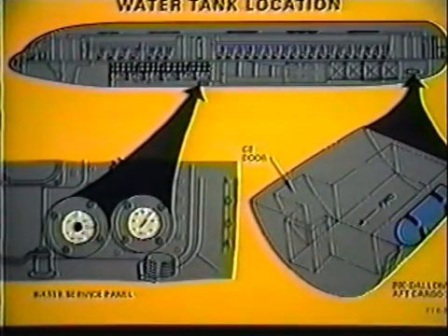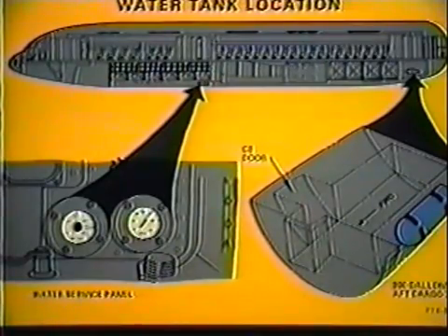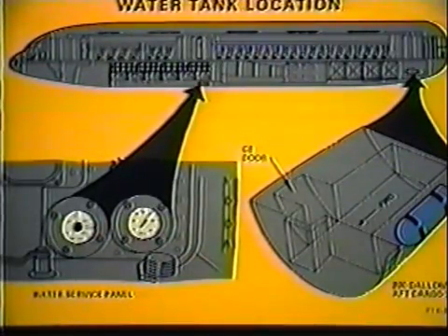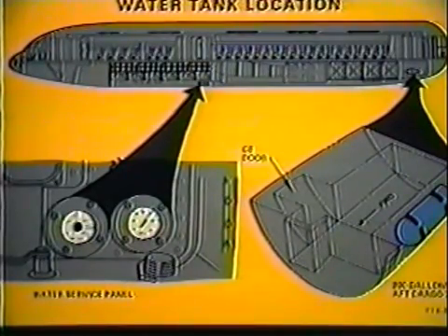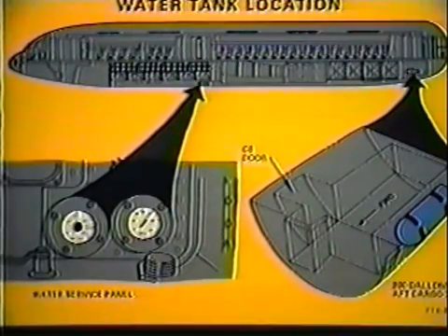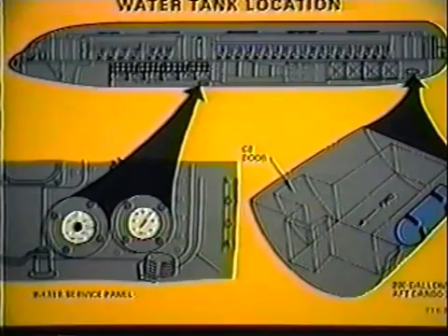The potable water tank on the Dash 500 aircraft is located near the aft cargo compartment. The quantity and pressure gauges are located on the water service panel on the outside of the airplane below the number 2 right door. This is the same location as it is on the Dash 1 aircraft. The flight attendants on this airplane do not have water quantity and pressure gauges inside the airplane. Consequently, the second officer must check these indications on walk-around.